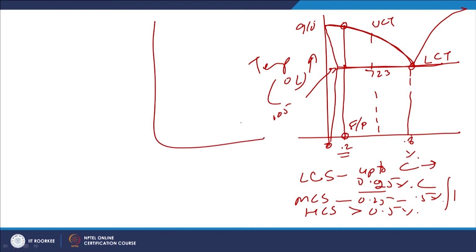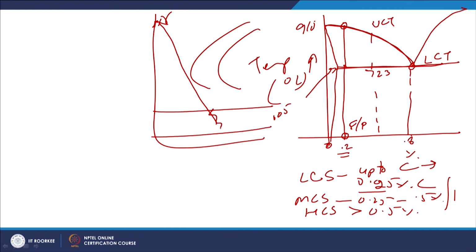Once we have got the fully austenitic state, then as per the carbon content, rapid cooling from the austenitic state will lead to the transformation of austenite into martensite and the required hardness. There is another aspect: the maximum hardness which can be realized through the austenite to martensitic transformation is also a function of the carbon content.